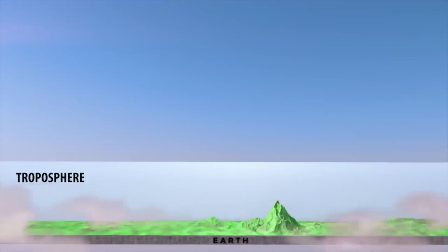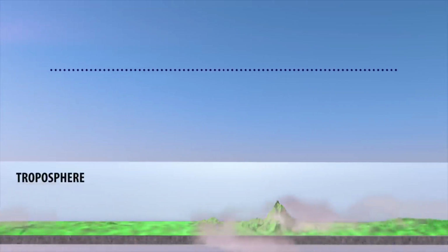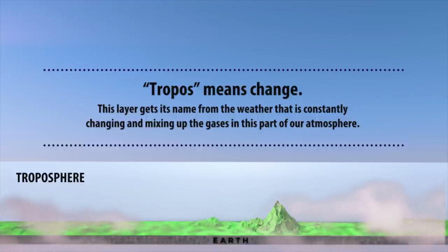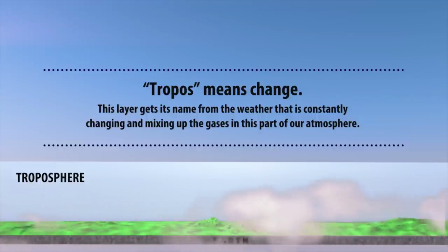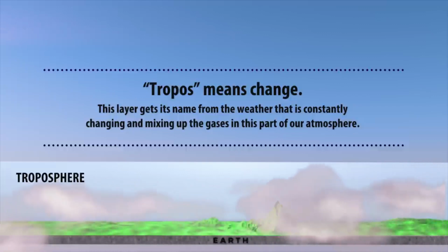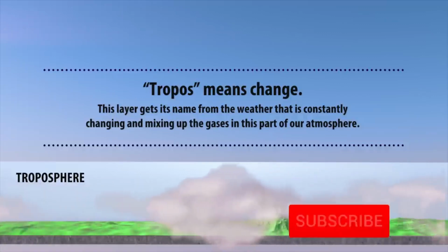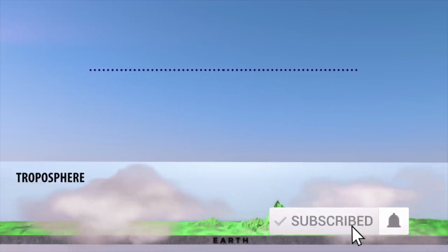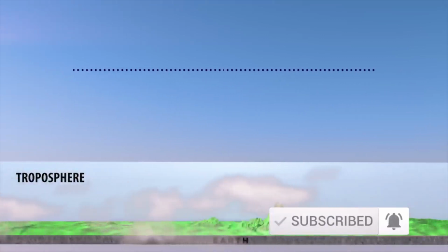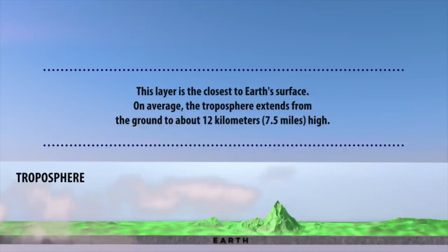International Standard Atmosphere, ISA. The International Civil Aviation Organization, ICAO, established the ICAO Standard Atmosphere as a way of creating an international standard for reference and performance computations. Instrument indications and aircraft performance specifications are derived using this standard as a reference. Because the standard atmosphere is a derived set of conditions that rarely exist in reality, pilots need to understand how deviations from the standard affect both instrument indications and aircraft performance.